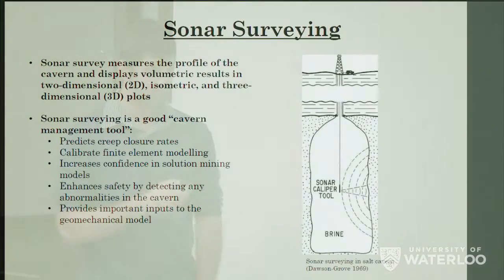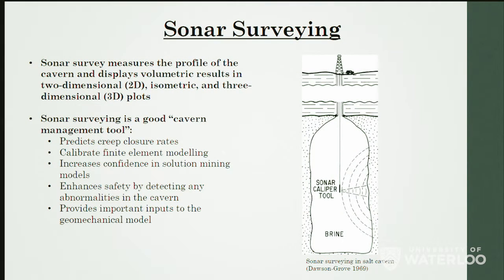The last monitoring technique is sonar surveying. In sonar surveying, a sonar caliper tool is lowered in the cavern, and it measures the profile of the cavern using sound waves. So the profile of the cavern can be measured in 2-dimensional, isometric, and 3-dimensional plots. Sonar surveying is a good cavern management tool because think about it.